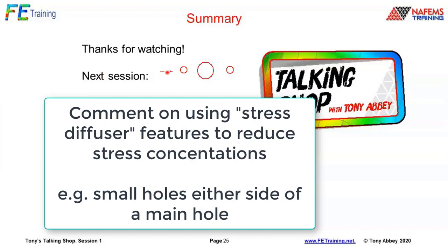We put a hole upstream, so now the stress is starting to change, starting to flow, so it's already flowing in a beneficial way by the time it gets to the feature that we're interested in. So we get a stress flow which has already been perturbed a little bit, and then it's going to be perturbed a little bit more as we go around here. It's the same idea as being entrained by the wall. As the wall gets closer, all these features can be very beneficial.